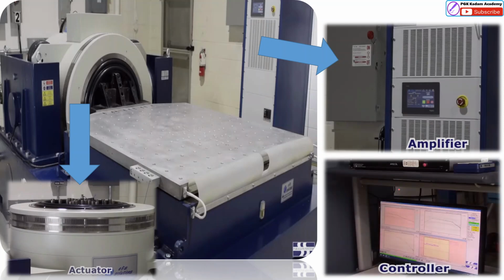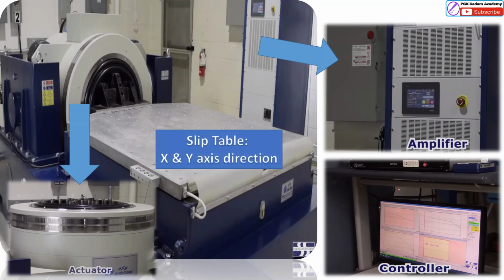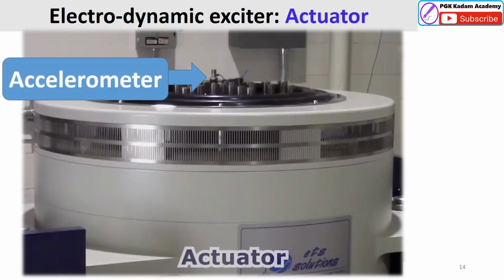The controller, in the CPU, gets all the readings and graphs, and we can store the recorded data. And this is the slip table, useful for creating the X and Y axis directions. The accelerometer on top of the actuator receives the acceleration and frequency signals from this electrodynamic exciter.